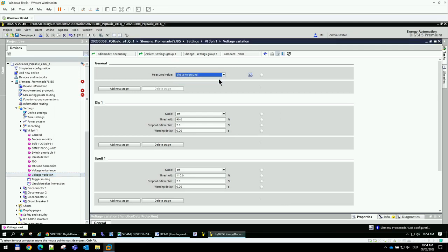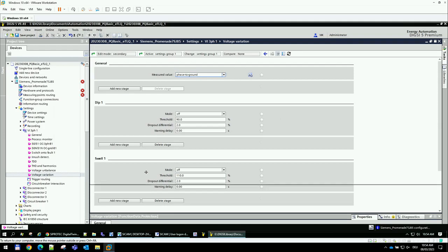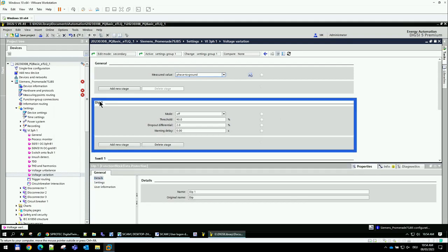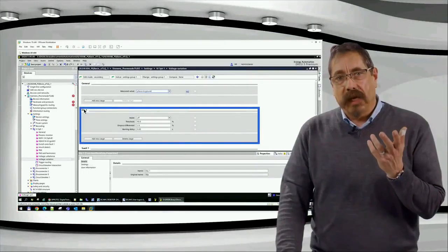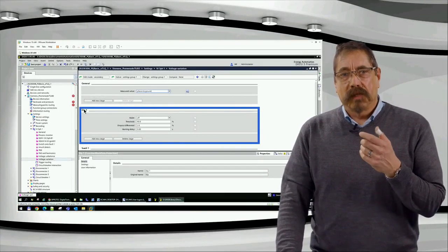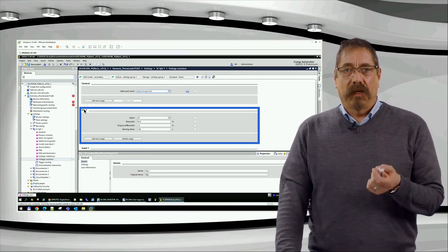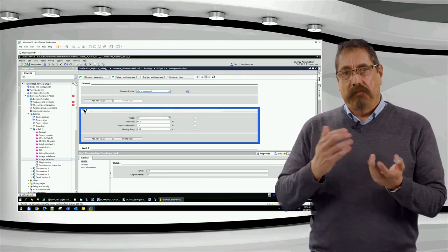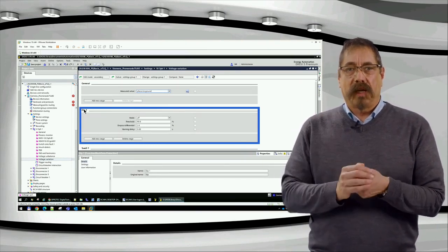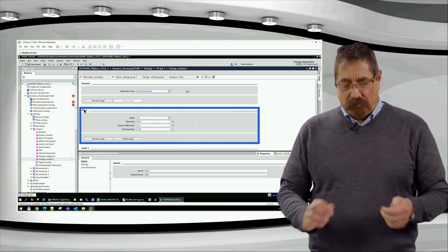So, and what I would like to do is I would like to rename the default names of these events to make it more clear, to make it already clear inside the name what is the threshold for these kind of events. This means we will define now a dip assigned with 90%, as well with 110, and then an interruption with 5%.